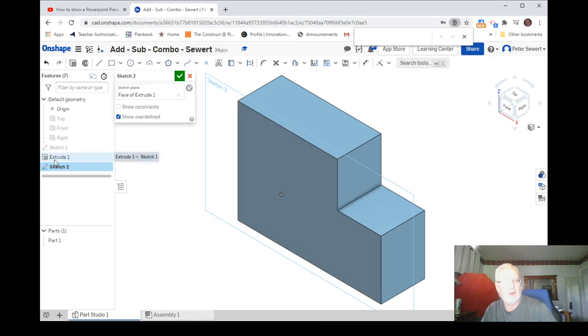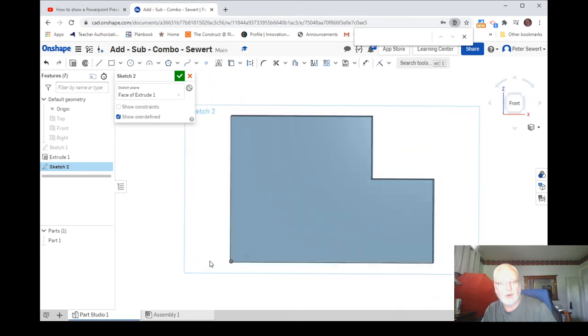And remember, we just did the extrude of this thing. There is the extrude for our initial block, part of the block. All right. Now, I'm going to use another command. This is called rectangle. And even though we're drawing a square, this is called rectangle. So I'm going to right click, do normal to, and then I'm going to use the rectangle tool right here.